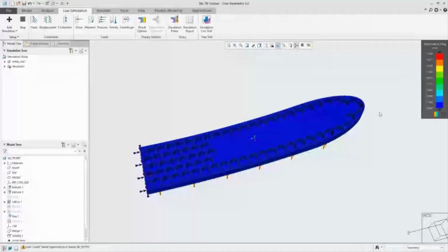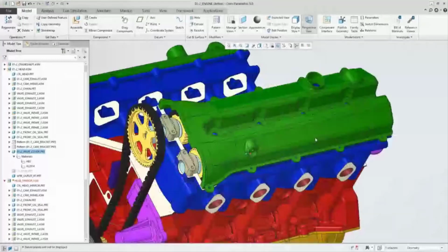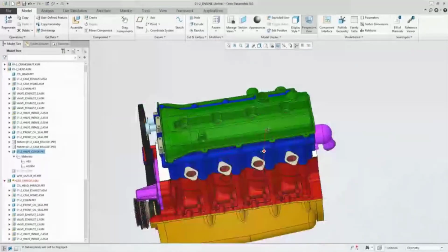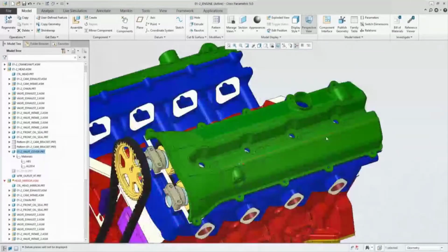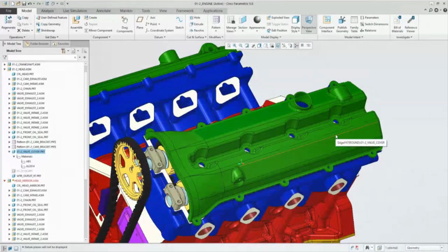The next one we're going to go through is a modal analysis, because as we all know, something very important for a design is to make sure we understand the relative stiffness and natural frequency of our parts. And this is an example of taking the intake of the engine and saying, well, right now it's made of aluminum. Can we do this in plastic? Lighter weight and a more cost-effective material. Now, I'm not saying cheaper here. I'm saying more cost-effective because it will cost less, but we need to make sure that it still fulfills the design requirements.